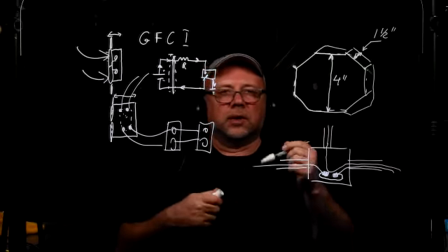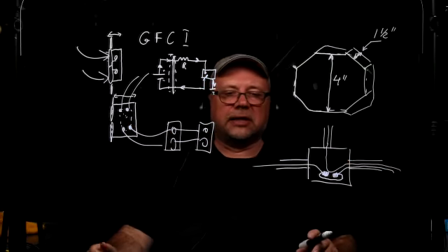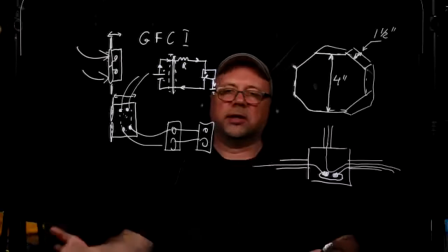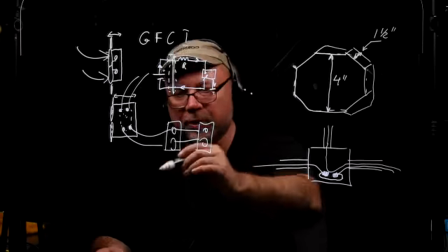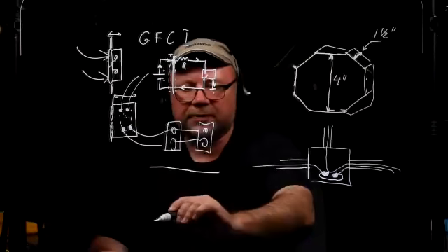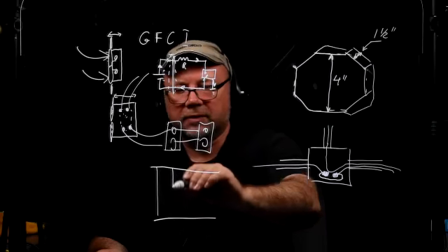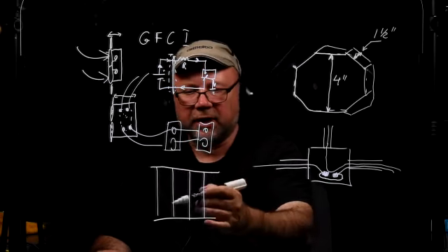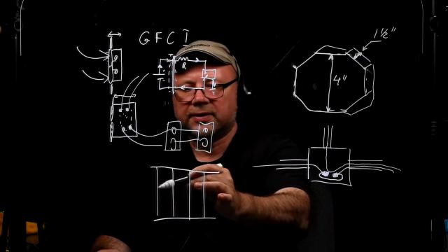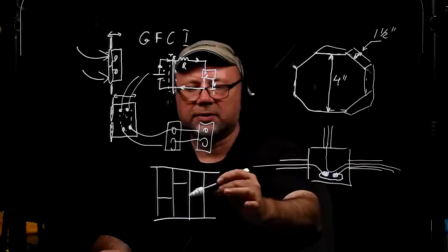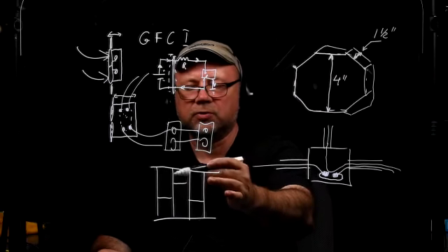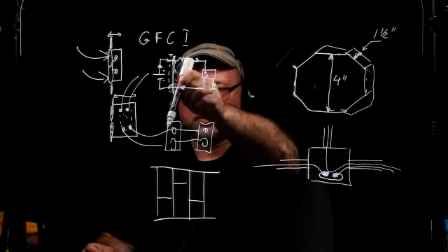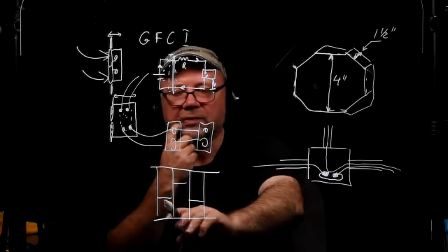Well, when you're installing the electrical devices, the drywall is gone, so just bare studs, bare framing is exposed. So here's the ceiling, here's the floor, and between that you will have metal or, let's say, wooden studs. Not a very straight ceiling, but that's okay. Sometimes you're going to have the horizontal notchings between those, sometimes not. Usually the wooden studs will have the horizontal notchings, and the metal ones are open from top to bottom. Good thing to know when you have to run a wire.